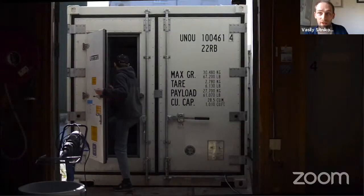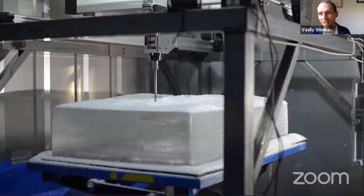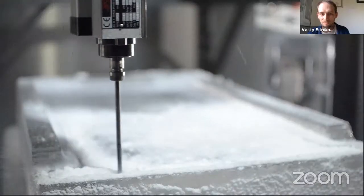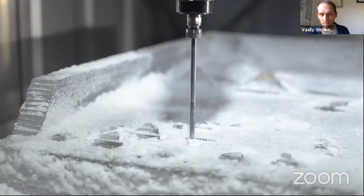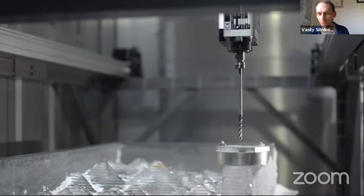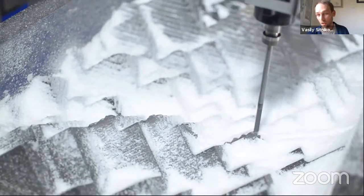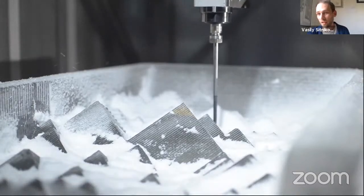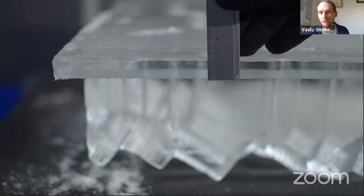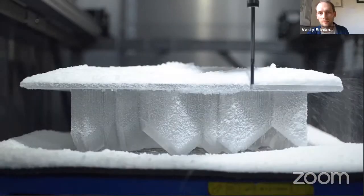So the refrigerator is actually quite easy to run, even though it's quite advanced equipment. We just go across the equator without maintenance. They're pretty robust. Here you can see how the ice is milled. First rough, and then there is a tool change. With a ball head, you then get the smooth surface finish. And even very sharp parts can be easily milled in ice. So there are no chipping effects or any processing limitations, I would say. It's definitely much faster than milling wood or milling MDF.